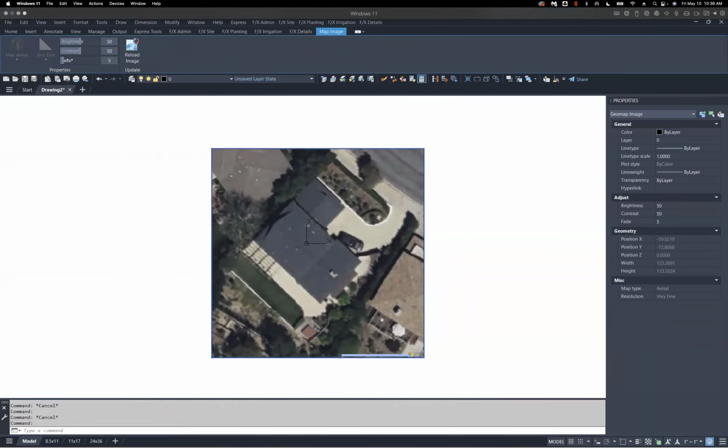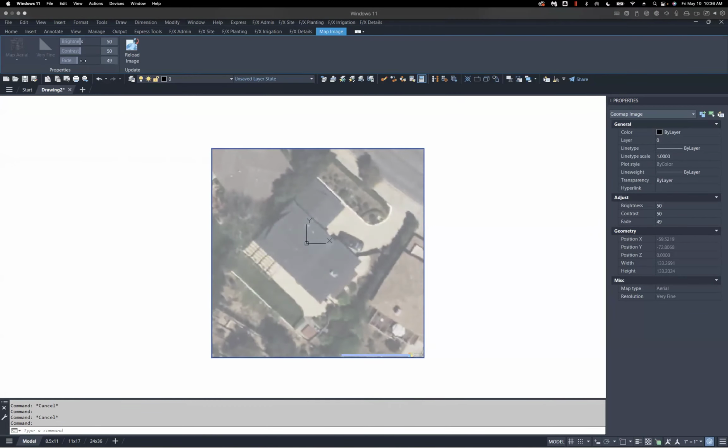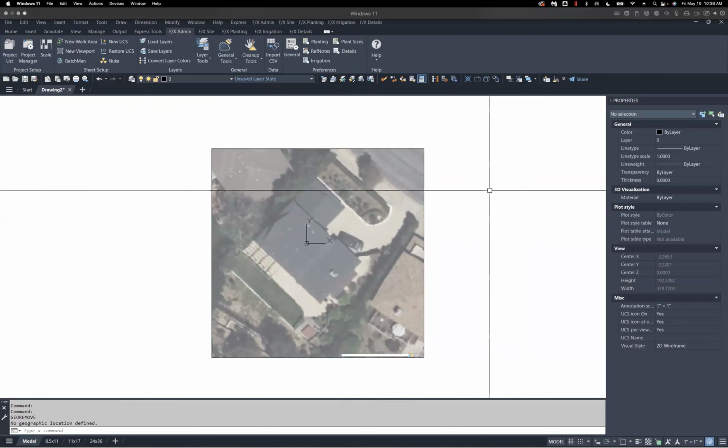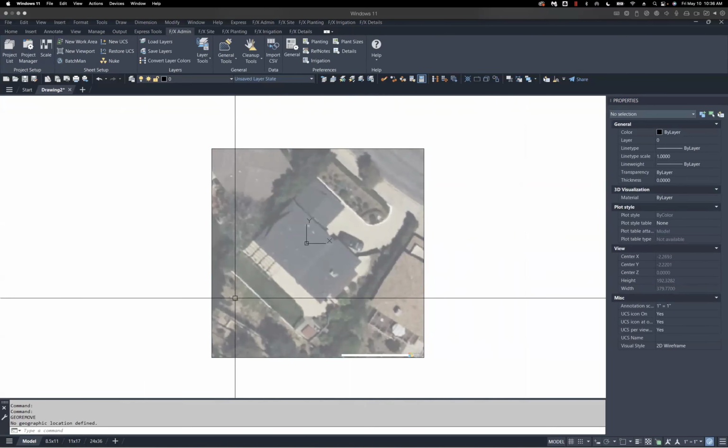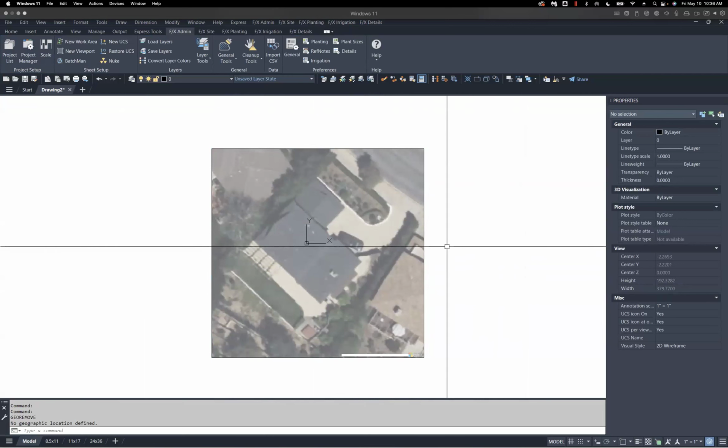This will be a personal preference thing that you'll have to play with as you work on your process. But I'm going to recommend that you have some level of opacity here so that when you're making your marks or your design, whether it's by hand or in CAD, the design elements that you're placing on this are going to really pop. They're not going to be drowned out by the background noise of the reference image itself. So that looks pretty good. I can just go ahead and click enter, and now I have that slight level of transparency set to this drawing.